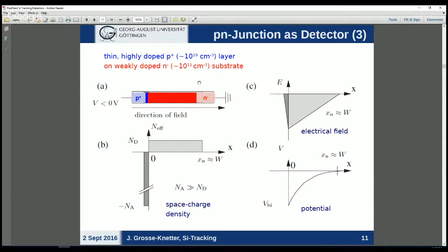And there's a reason for this, and it's not because we can't do better. In the end, this entire device has to stay neutral. So when you have this recombination of electrons and holes on either side of the junction, they have to combine one by one. One hole gets one electron, and then you're left with a space charge. That means in the part of the device that's weakly doped, you have to evacuate a much wider volume of charge carriers than you would have to in the highly doped part.